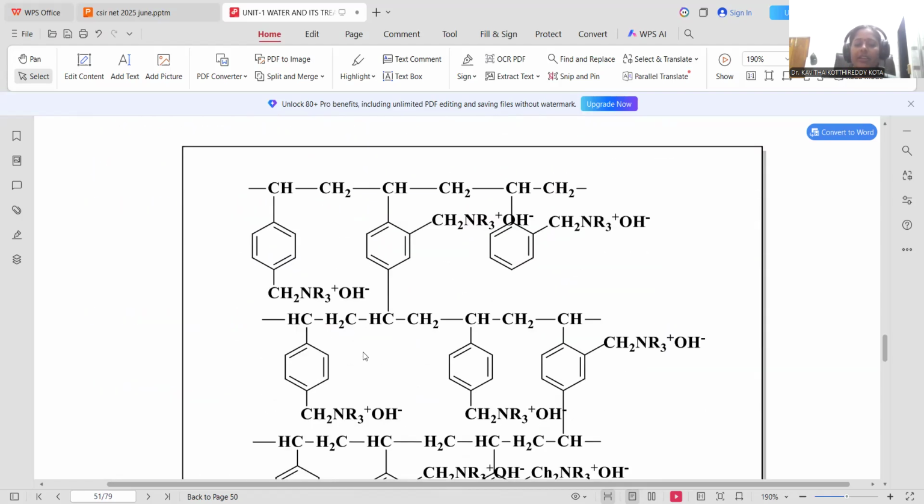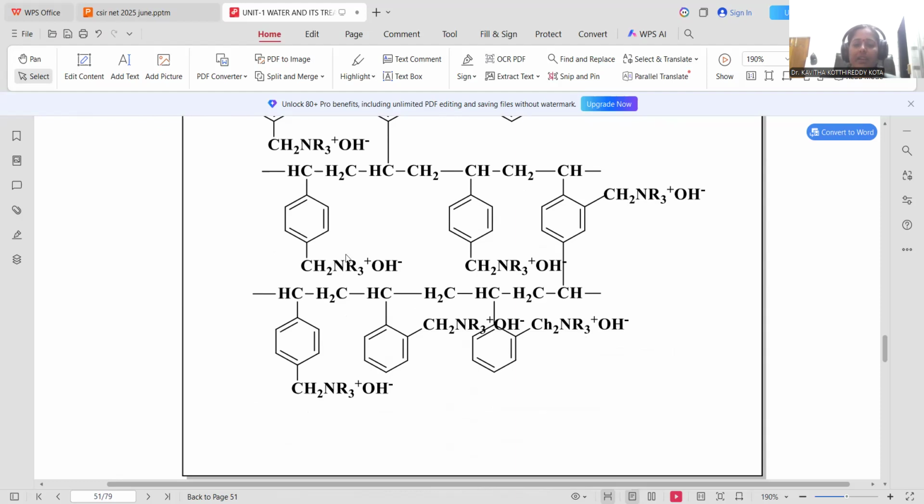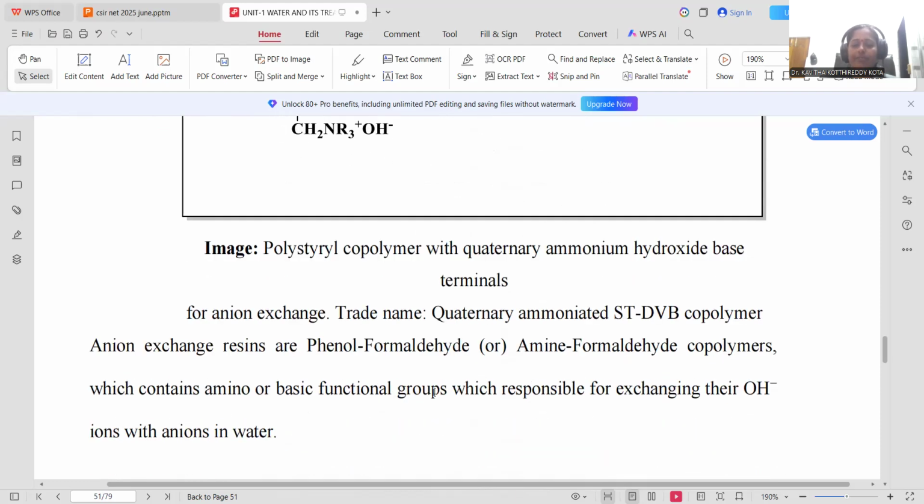Now it turns to enter into an anionic chamber where you can observe again the styrene skeleton which is cross-linked. There is a provision for the free release of hydroxide ions and the quaternary ammonium cation. These quaternary ammonium hydroxides have more susceptibility to release hydroxides into the water, so that anion exchange is taken conveniently, and this kind of anionic resin is suitable for all the anion absorption.